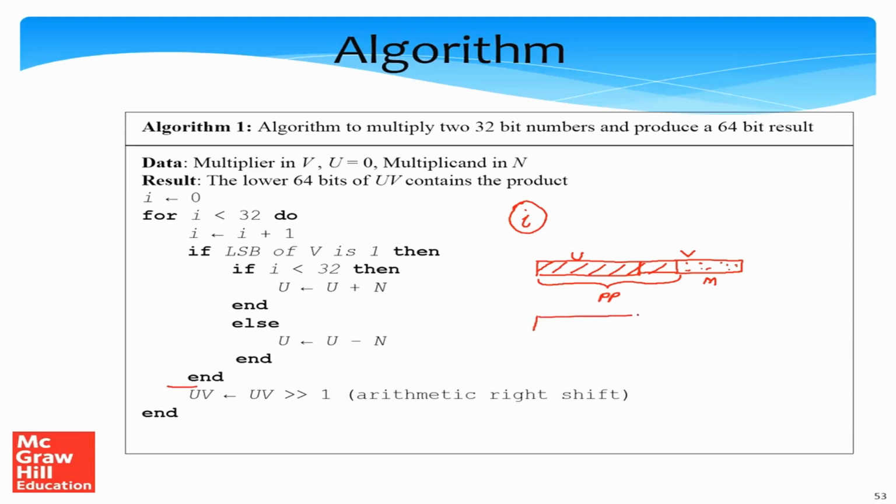So effectively what this means is that we have one bit. Basically, when we shift it to the right, we maintain the sign bit as well. But disregarding that, the partial product is pretty much contained in this fashion. This is for register U, and again for register V, the partial product will again come here, and we will have the remaining set of multiplier bits, where one bit just fell out because of the right shift operation.